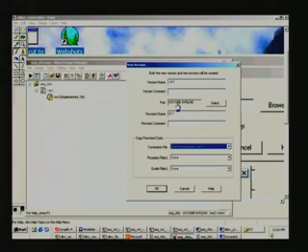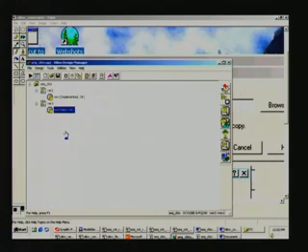Instead of 50E earlier, it is 100E, and this constraints file we have just seen is a previous version, which is exactly the same sequential circuits UCF file, and once you are satisfied with all this, just say OK. So, version 3 revision 1, and here it reports a new version is created.